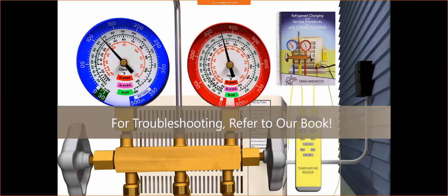What ends up happening is once we're in an ice making state, there is no reversing it. That system's going to continue to run, and it's going to continue to keep making ice until it turns into a big frost ball. Once that happens, we can't adjust the temperature, we can't adjust the pressure, we have to let that ice fully melt. Once it melts, then we're able to come back in, fire up the system, see what's going on.